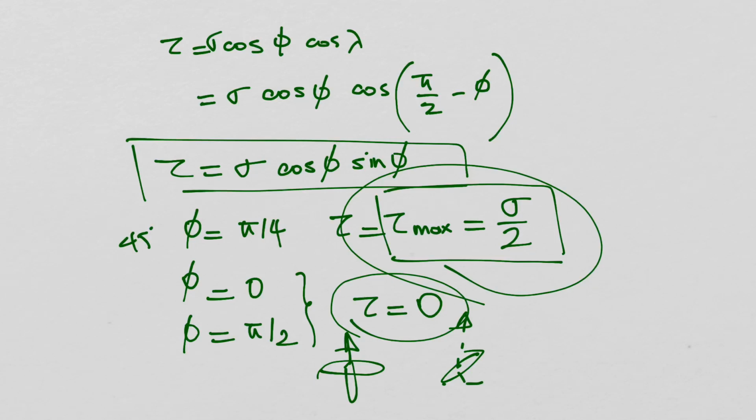So those planes where you reach the maximum are going to be the most favorably oriented slip systems, because the resolved shear stresses will be the highest there, and of course the possibility of that getting above the critical shear stress is much higher. That's why the slip happens on those planes, when the resolved shear stress is the maximum.